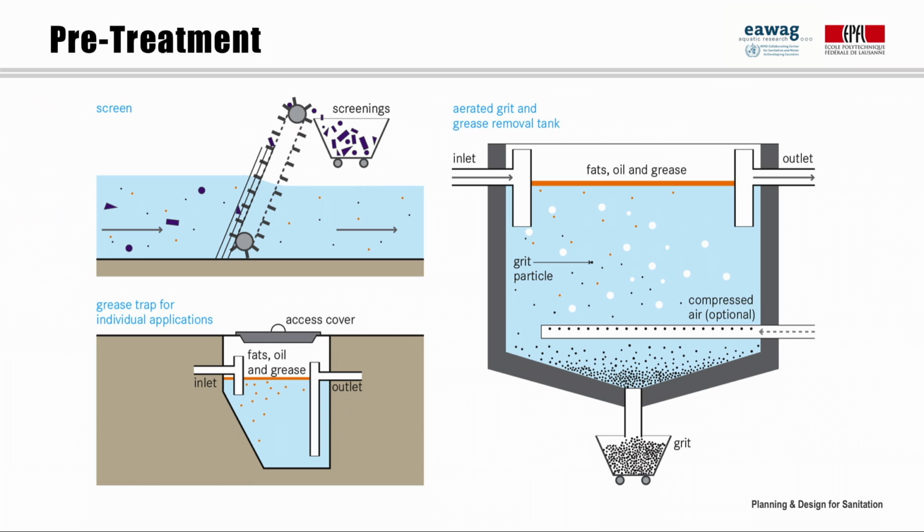Pretreatment is a preliminary removal of wastewater or sludge constituents, either before conveyance or before treatment systems. It is meant to prevent the accumulation of solids in further stages and avoid blockages. It can also help reduce abrasion of mechanical parts and extend the life of sanitation infrastructure. Pretreatment technologies use physical removal mechanisms such as screening, flotation, settling, and filtration.